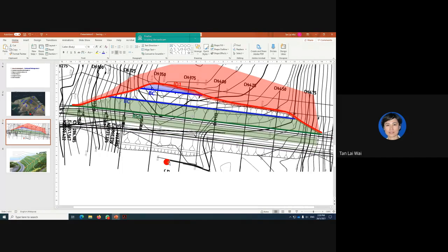Here's the thing: have you ever seen a road or a drain design where upstream is small, then coming to downstream it is large? No, it's a constant size, right? Agree? Yes. So when the size is constant, definitely you want to design for the part where it has the most discharge or peak flow.